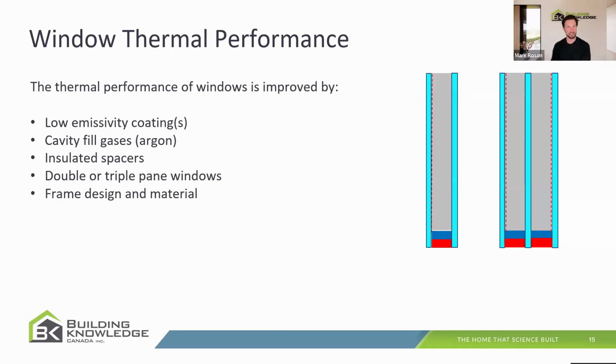Adding panes of glass. This is very much in the public dialogue today. Triple glazed windows versus double glazed windows, triples versus doubles. More glass equals more air spaces equals higher insulating values for your glass units.